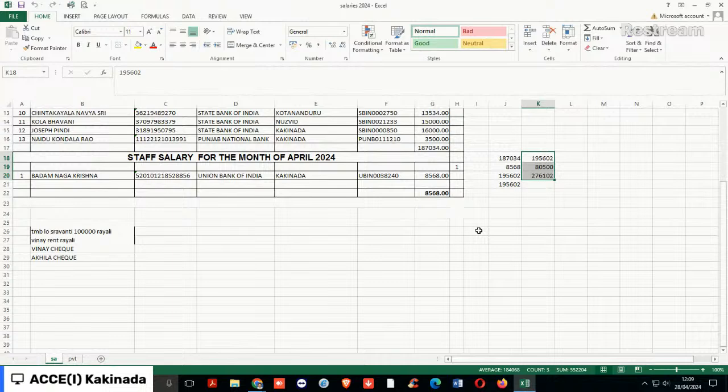That should be effectively resisted, similar to a gravity load shear. That is what we call diagonal tension cracking. This diagonal tension cracking is the second mode of lateral load behavior. For this also, you have to confine with stirrups, with a hook of 10 times the bar diameter or 135 degrees, or 4 times the radius, and also a minimum 75 mm end length. All these criteria are necessary to keep the lateral tie effectively in place.